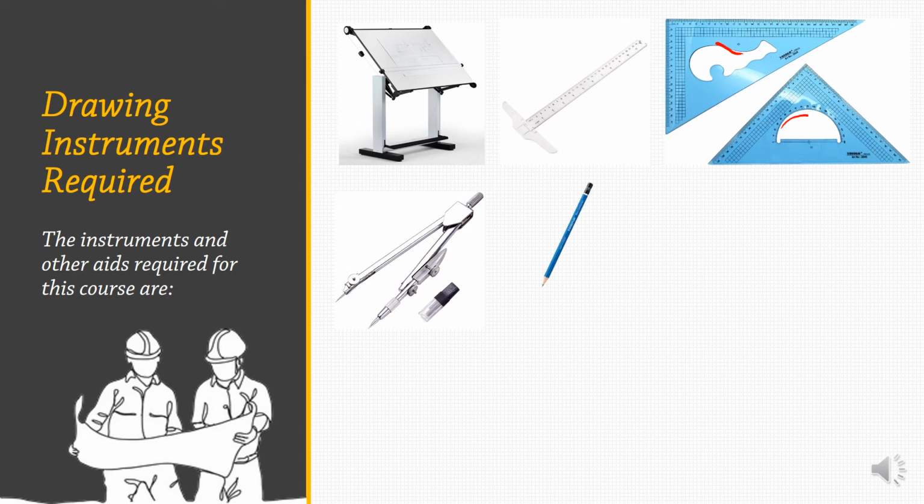Next is the drawing pencil. You need a 2H and an HB, or you can use a 0.5 mechanical pencil. It depends on you, an HB drawing pencil or a 0.5 mechanical pencil. So two: 2H and HB, or 2H and a 0.5 mechanical pencil. A mechanical pencil is not expensive unless it's really branded, but it is very efficient to use because you no longer sharpen and the thickness of your lines is uniform.